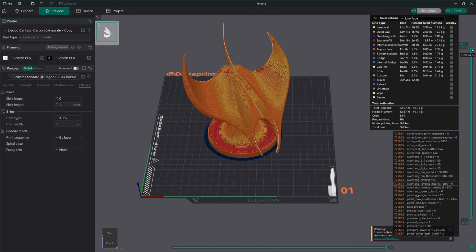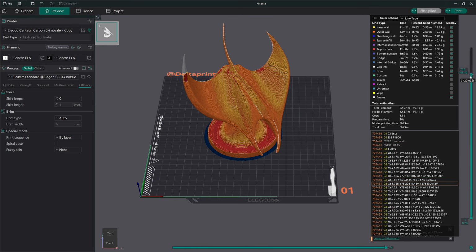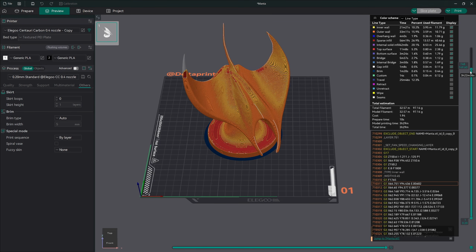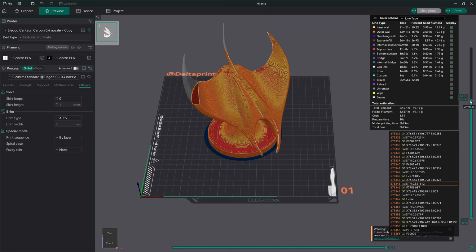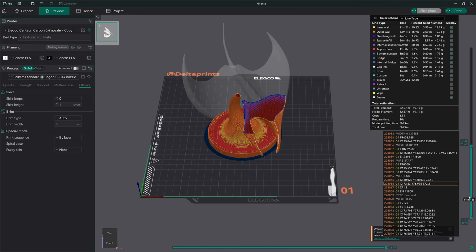Now this layer widget is a great way to run through your entire print. You can move the circle with a plus up and down to display a particular print layer. This is good for times when you have a failed print happening at a specific layer. You will always be able to drill down to that point and investigate it. You can also hover your mouse over the entire bar and click, and the circle will jump to that position. At the bottom of the layer widget is another circle that you can actually move up to a specific area of your print if needed.